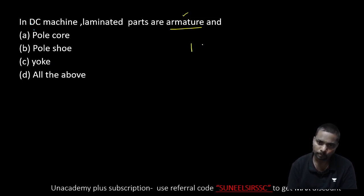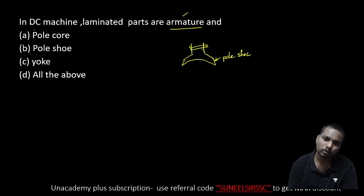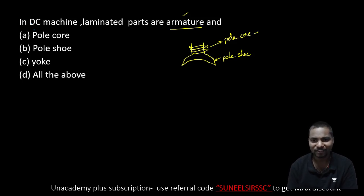The pole is generally divided into two parts. One is pole core and one is pole shoe. This is the pole shoe, guys. And this is the pole core. For that we are doing the winding. This pole core already has less cross section area, so in the sense that the eddy current losses are already less. The pole shoe has a wide area, so there is a chance of eddy currents.